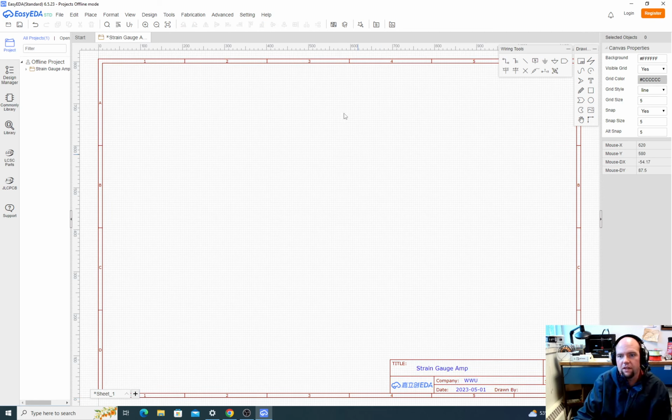So typically with this sort of thing, in a big company, there's going to be a draftsman who's going to do the schematic, and then there's going to be an engineer who's going to do the hardware layout. So a lot of times you can design a circuit in a schematic, but there's things you need to know about how to physically structure that circuit that are going to matter. So for instance, if you have a USB connection, the USB data lines are very high speed. You can't just run the wires however you want across the board. They have to be kept close together. They have to be kept over a ground plane. There's a lot of rules for that. The person doing the drafting might not necessarily know those rules, whereas the person doing the PCB might.